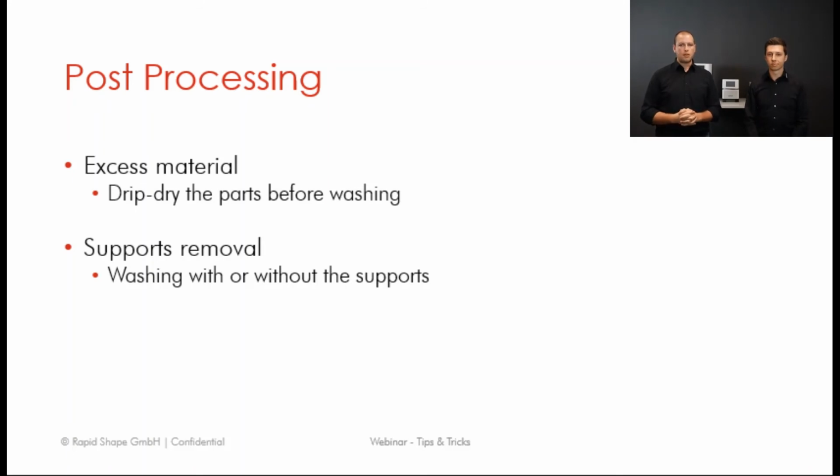Then we also have to look at the support structures. Again, this comes down to the design. If you have a very delicate structure, then you might have different results, because if you are post-processing supports that are adhered to something, but the supports are so nimble that they will just break off during the washing cycle. It is important to note that the type of washing cycle you use will determine whether you remove these supports before or after.